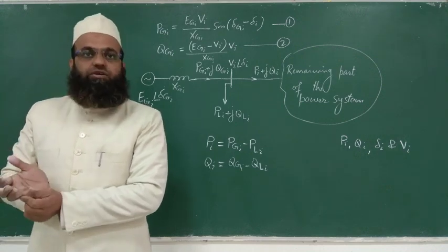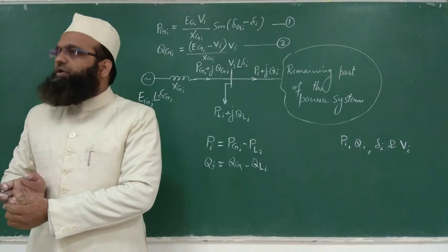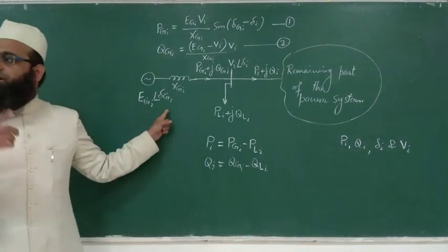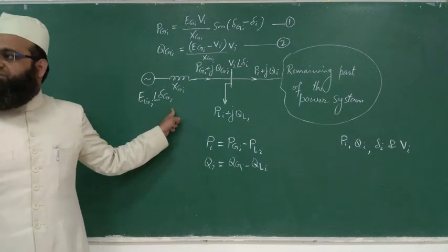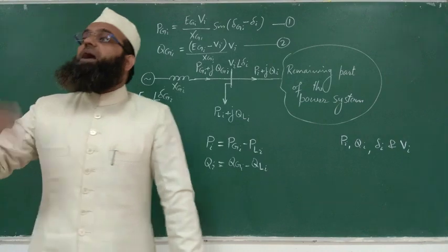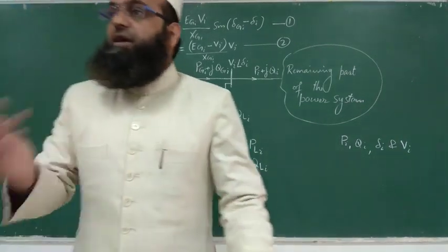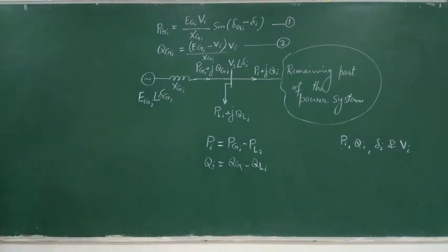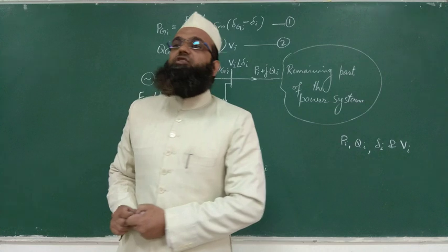That may be a capacitor, synchronous condenser, etc. It can't be controlled beyond the capacity. Within the capacity, we talk within the capacity. If still the demand is more, then you need to add capacitor banks, condensers, etc. Right? Okay, so next we will see how to control bus voltages with the help of transformers.